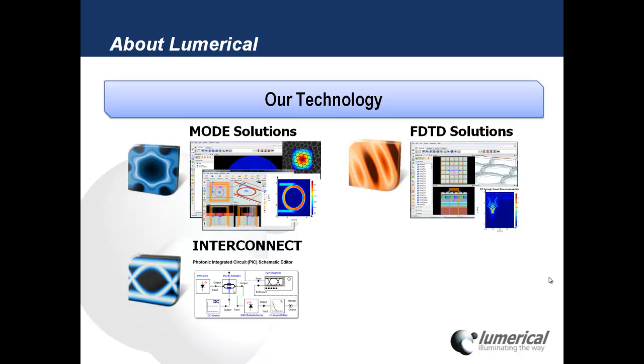This year, in early 2012, we added Interconnect, which is a photonic integrated circuit simulator, and it allows us to simulate circuits at a higher level of abstraction, more similar in concept to SPICE modeling for electrical circuits. And so this allows us to look at very, very large circuits and systems and to look at their overall performance in terms of S parameters and also in terms of signal integrity analysis in the time domain, looking at things like eye diagrams.